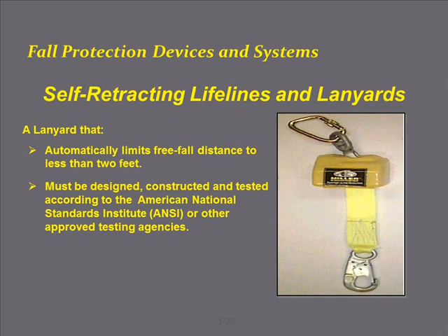A self-retracting lifeline and lanyard is a lanyard that automatically limits its freefall distance to less than 2 feet. It must be designed, constructed, and tested according to the American National Standards Institute or other approved testing agencies.